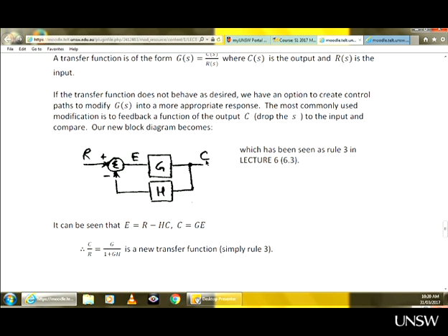So if that system, a spring mass damper system, is to represent the suspension of a car, it will be different. That stiffness K will change slightly with temperature. The mass of the car will change depending on how many passengers we have in the car, and so on and so forth. So there are so many things you can't always predict in real life, so you don't always get the output you want. Not to mention there are some perturbations that, again, we don't model with a block diagram like this, but they may be present, and again, change the response, change the output from what we want to something we don't want.